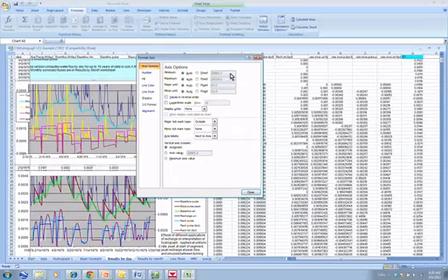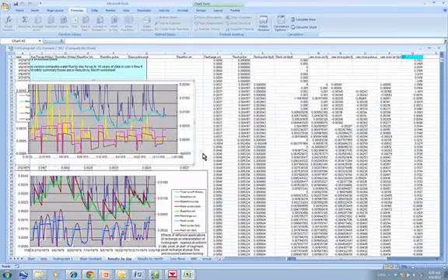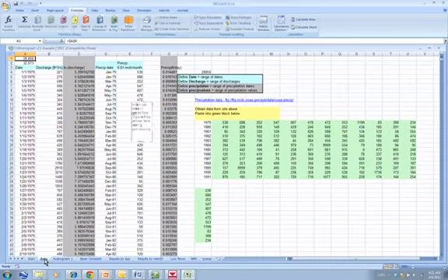In this case, this plot is giving me what I want for a range, but what can happen when you enter your data is that it'll be a different range than was used in the analysis previously, and the plot may not show any data at all because the range here doesn't move with the data necessarily. So if that's the case and you want to reset the range, just go back here to the data and use these numbers right here to reset the range of the plot, and that'll get you back on scale.